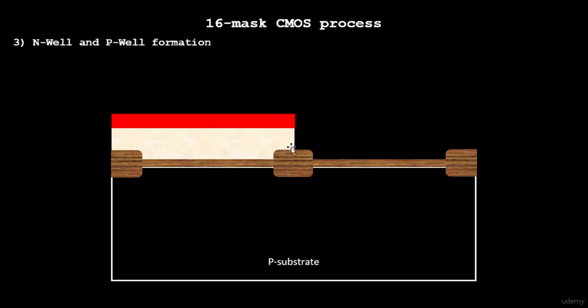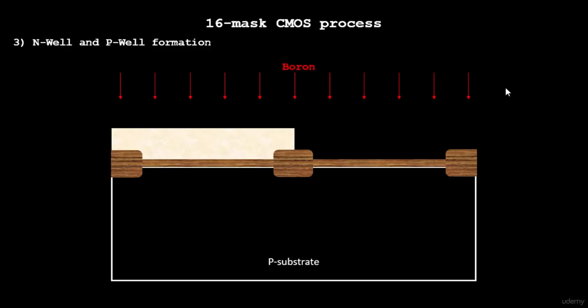Now when we remove the mask, there is this small area and this small area, under which if you do certain kinds of chemical actions, or some kind of deposition or etching, it will affect only the exposed area and not the ones underneath the photoresist. So it's a protection layer for you. That's very common, and that's the reason we have all this custom layout that we are going to discuss. This is just an example of how the layout helps you do a photolithography process while you try to fabricate your chip onto a silicon substrate.